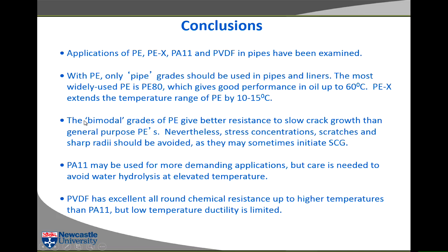They're actually bimodal. They have a special molecular weight distribution in the polymer, and they get better resistance to crack growth than general purpose polyethylenes. Again, more about that later. Nylon 11 is used in more demanding applications, particularly with oil at higher temperature, but you need care with nylon 11 because it's attacked by water at high temperature. So if you're using nylon 11 to handle oil from an oil well, you're not supposed to have more than 5% of water in the oil.